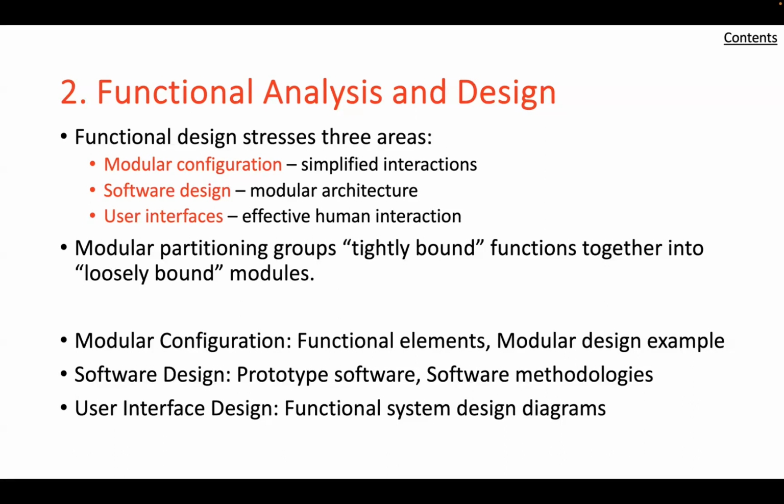Even worse, adjusting one also affected the performance of other interacting components, and as a consequence, the missiles regularly failed to pass their final acceptance tests. This problem effectively stopped production until extensive redesign was accomplished to increase component tolerance, eliminate most of the adjustments, and make individual components much more independent. Ultimately, it required complete reconfiguration of the components some years later to a highly modular form to make the production process relatively effective and efficient.